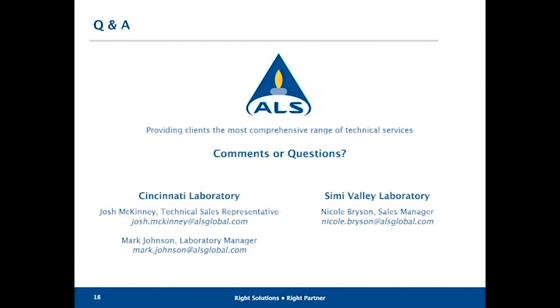Okay, and it looks like someone just wanted to make a comment in regards to helium tracer analysis. It says even if the lab can check for tracer gas, it's still a good idea to conduct the leak testing in the field. Field testing will reduce the possibility of poor quality data or the need to return to a site later and resample.